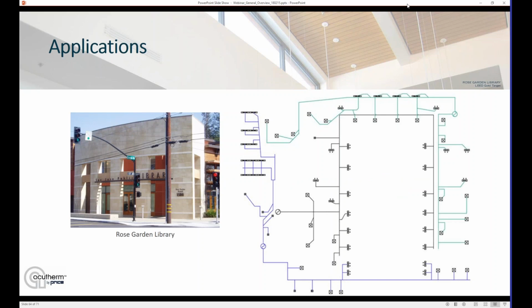So there's a zone on the left bottom of this drawing. There's another zone on the top right and a third for the interior. And the nice thing there, as I mentioned, no need for reheat. When one of those zones needs heating, the whole zone can go into heating. That means you're really eliminating energy wastage from reheat, as well as reducing pressure drop in your system. This is an all low pressure design system, and then fan speed control to provide the pressure control into the system. And then those Therma-Fuser diffusers, sub-zoning each of those zones, providing that individual control throughout the space.